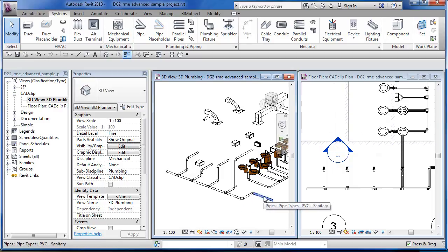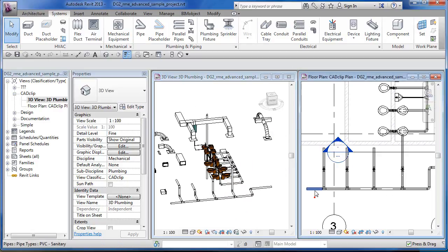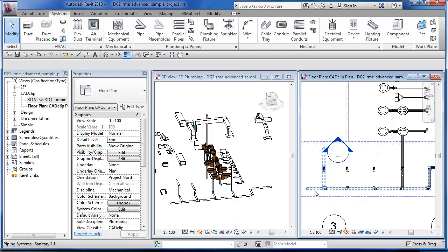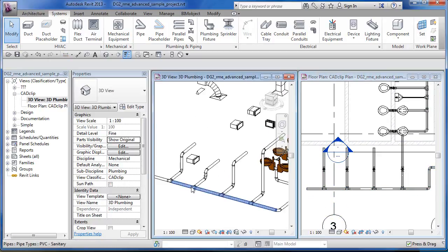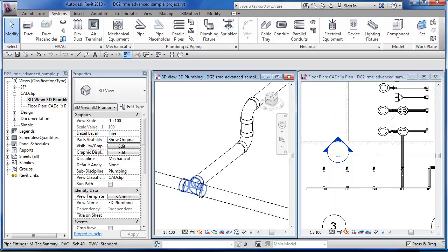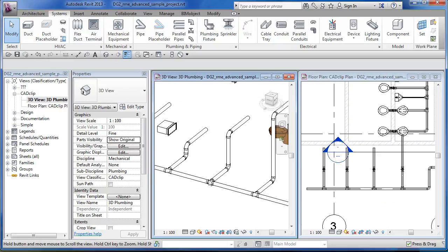So watch, if you hover over here as normal, Tab grabs that main branch, and then Tab, Tab, Tab, Tab, Tab. Where is it? I want to grab them all. It's not highlighting them. What if I try it from here? Now, is that because they didn't get connected? Yeah, that is. That pipe goes right through. These guys did not get tied in.